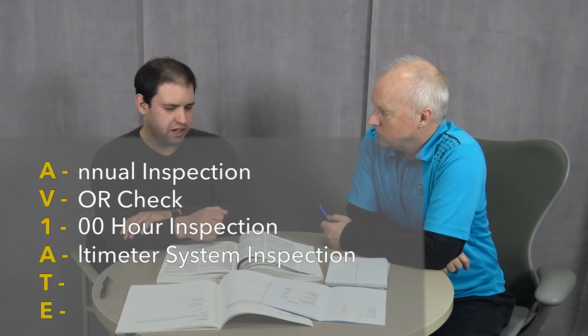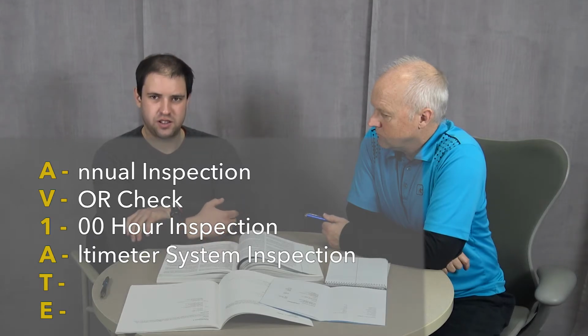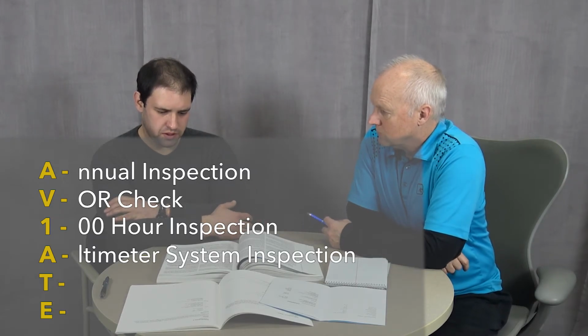Every 2 years, 24 calendar months, you need to have the altimeter checked for accuracy by a certified maintenance shop that is capable of doing those checks. The airplane that I own personally is not certified for IFR, so I'm not required to do that altimeter system check, since there's no reason to.